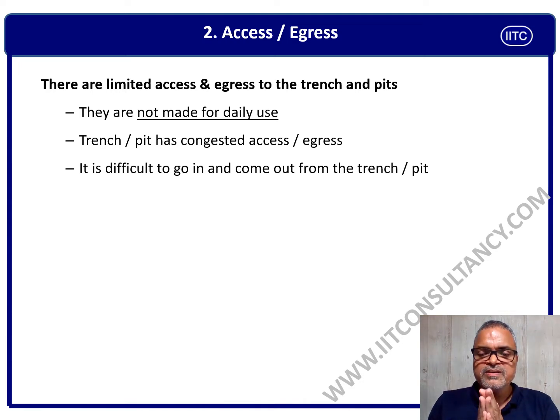The second very important hazard of excavation is limited access or limited egress, because excavations are not made for daily use. You agree with me, right? We do excavation for some non-routine activities, for some construction or something. Secondly, trenches and pits are congested in terms of access and egress.